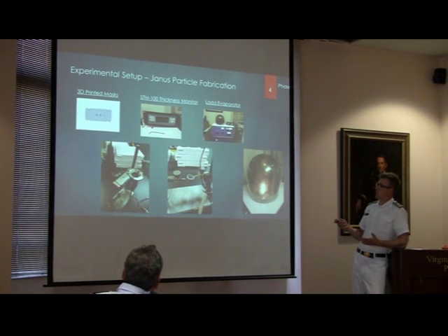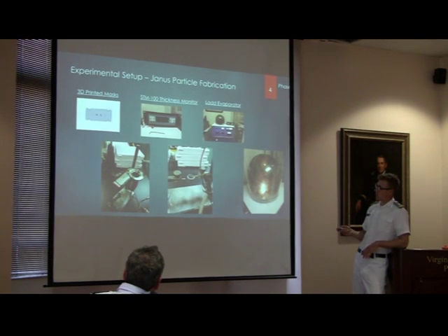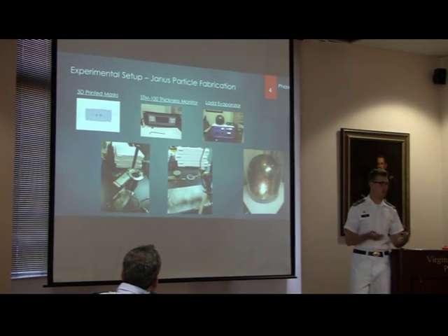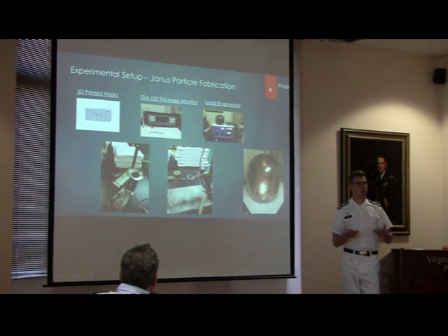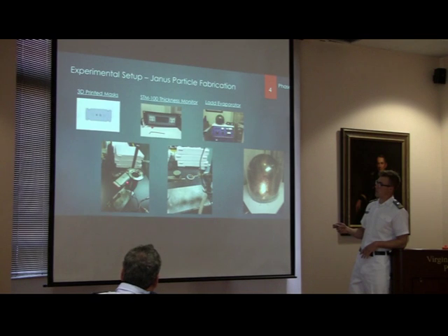So in this evaporator, really attached to the side, is this thickness monitor. This little black box is wired up to here. When the nickel, which is our coating, we would evaporate onto the bottom, when we take this metal, turn it into a liquid and quickly into a gas to go onto the bottom of the part and give it a coating, it also coated the bottom of this here, which is a small quartz crystal.